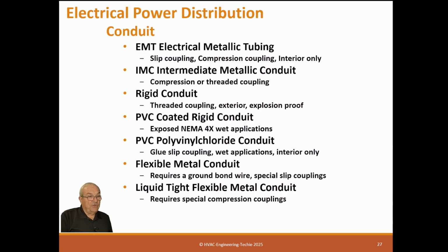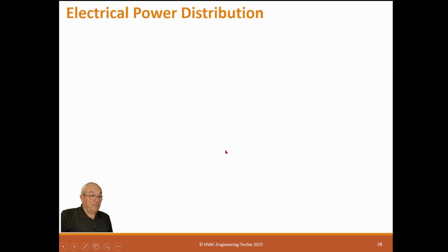However, they are not UV resistant, so the sun will eventually eat the PVC coating up on it. So they actually need to be either covered or coated with a coating that protects them from UV damage, or else they won't last that long. Depends on your environment, but here where I'm at, 10 years maybe, if you don't have them coated.